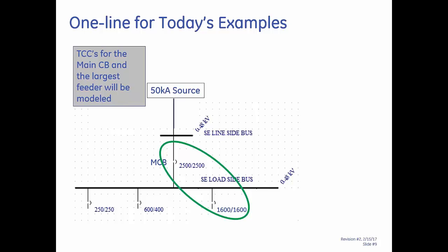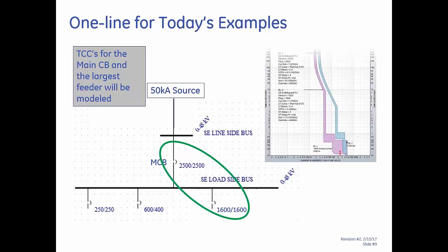So you can see not only the arc flash implications, but also the close cousin selective coordination implications of what we're doing. So here is going to be the baseline setting of the main breaker shown in cyan, and the downstream 1600 amp breaker shown in purple. Obviously, there could be different ways to set these up as a baseline, but I think this is a fair baseline setting that also will allow you to see, as we progressively try the two technologies we're going to work with, exactly what's happening in the time current curves.